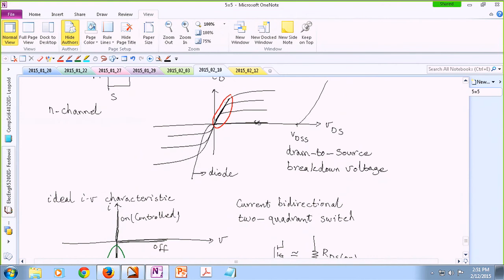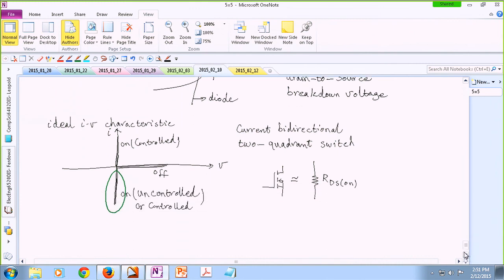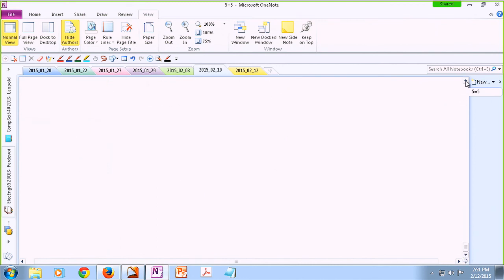Okay? So remember, when an IGBT is on, it is pretty much behaving like a constant voltage source, like a saturation voltage value of, for instance, 1 volt or 2 volts or 1.5, something like this. When your MOSFET is on, it behaves like a resistor, and the value of this resistor obviously depends on your device, but to give you some ballpark numbers, like 50 milliohms, 100 milliohms, 150, 500, something like that. It's in the order of milliohms. It's not that much. One other interesting thing about MOSFETs to remember is, as the device gets warmer, this resistance that is representing the device when it is on actually increases, which is unusual usually.